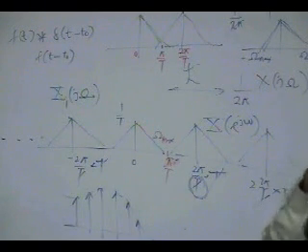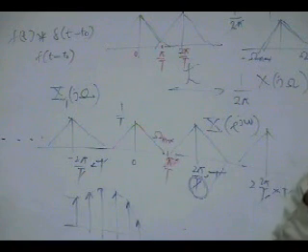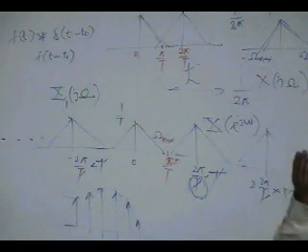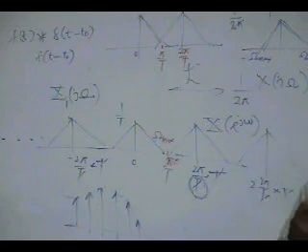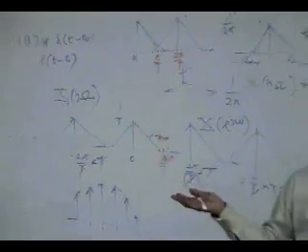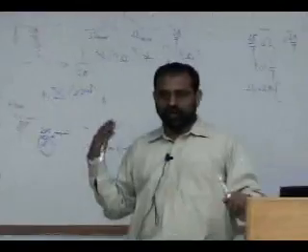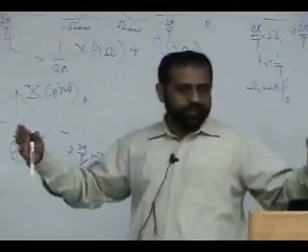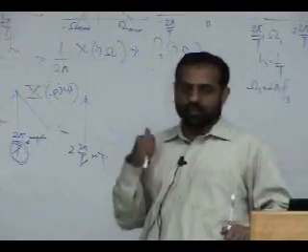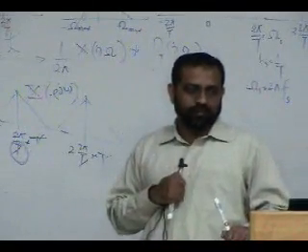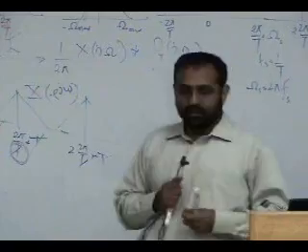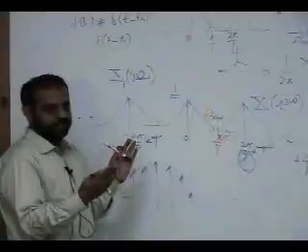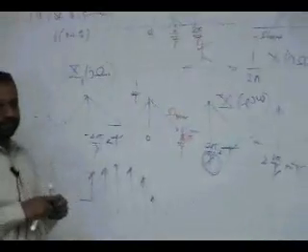So the thing in your hand is an appropriate A to D converter. You say I will use the higher speed A to D converter to capture the spectrum. People usually capture a lot of garbage. Okay, if you have a faster A to D converter, it is always better to capture a wider spectrum, then clean it up in the digital domain instead of using analog filters. This is done a lot. If you can spend money to get a wider spectrum, which is fine, and then digitally throw it away.